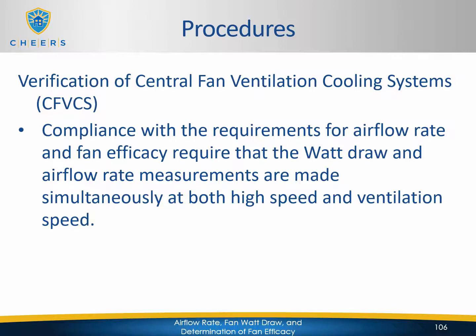Well, a central fan ventilation cooling system does just the opposite. It's going to use a duct that goes to an outdoor inlet, so it's going to have access to the outdoor air. And again, when it's cool outside, it's going to use the return side of the duct system to draw this cool air from outside into the central system, and then it's going to distribute that through the ductwork to all the different rooms. Again, you're either going to have to open your windows or have some kind of a damper system that has outlets up into the attic.